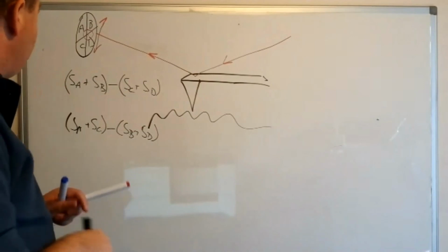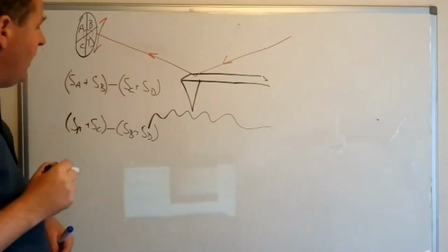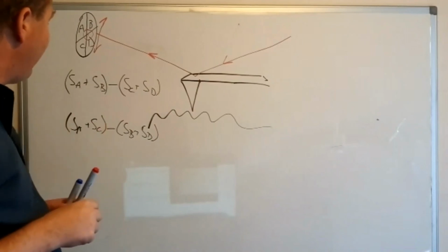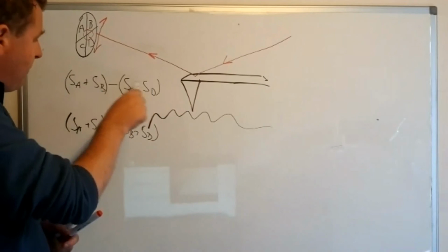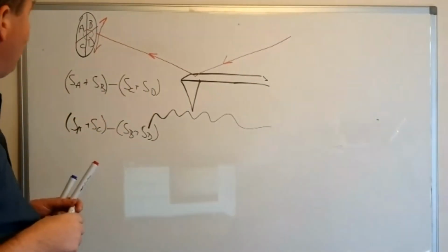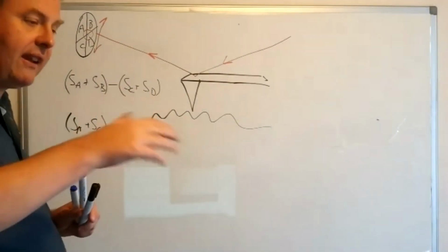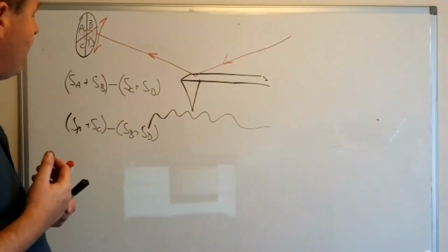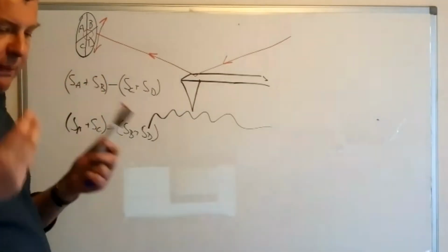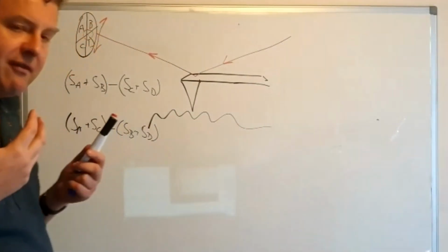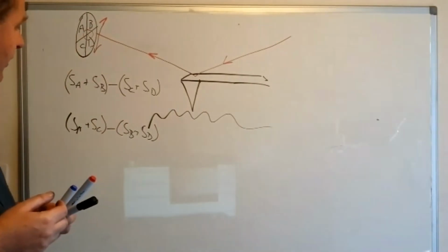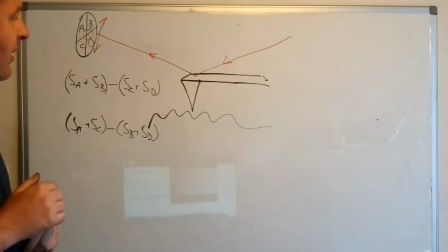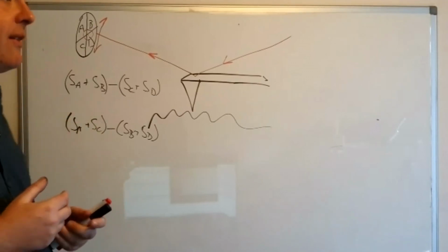So although the signals of these things each may not be changing very much, and they're starting from quite a large background level, by looking at the differences between these signals, you've got this null detection scheme going on, and you're able to get a better, more sensitive measurement. So it's always worth, when you're trying to work out how to get a good measurement and you have a sensor which is giving you a large background signal, to try and set up some kind of null detection routine in order to cancel out the unwanted background signal. So typically, as I say, using potential dividers or subtraction.